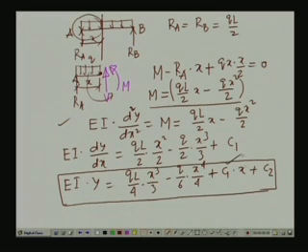Now, we will have to evaluate the values of C 1 and C 2 with the help of boundary conditions. What are the boundary conditions we have for the simply supported beam? If we look into the deflected profile, the axis of the beam is going to deform in this form. Since this is a hinge support and this is a roller support, at x equals 0 the deflection is 0, and also at x equals L, y is equal to 0. So, these are the two conditions we have.